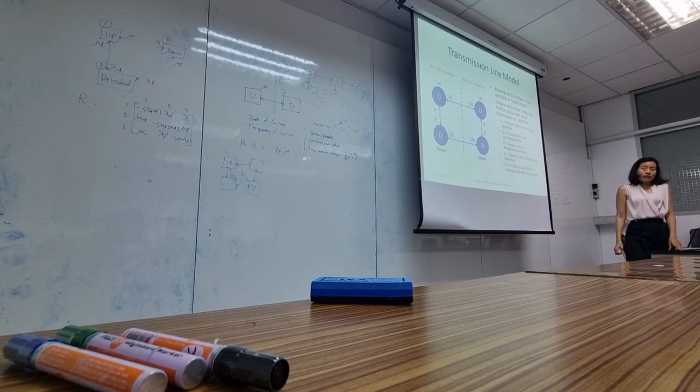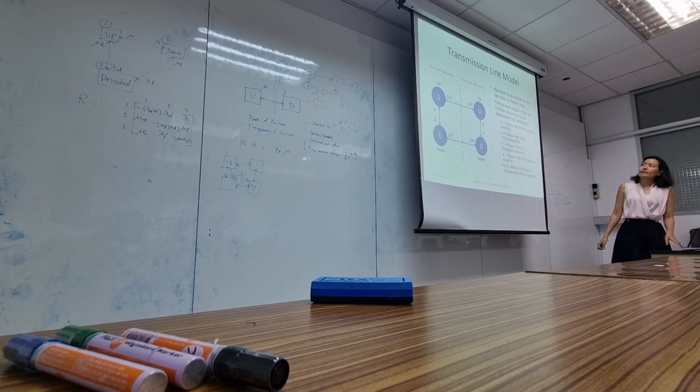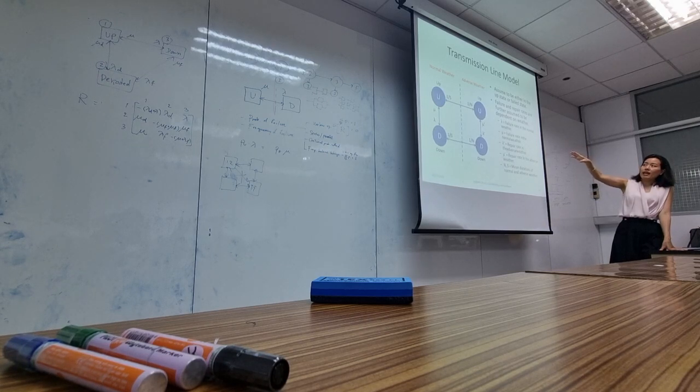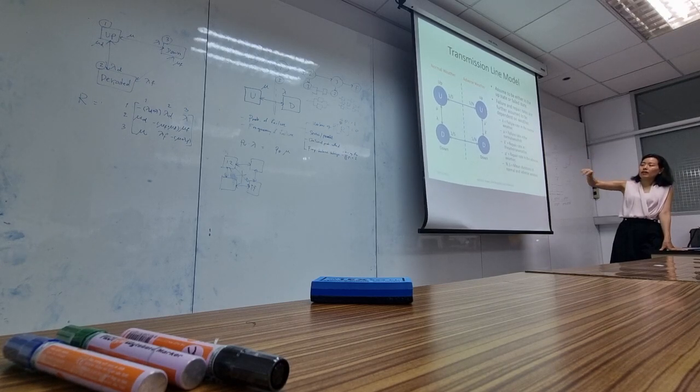Okay, forced outage rate. So we look at that example. For the transmission lines, they assume two states only. The up state and down state. Up state with full capacity and down state with zero capacity. But in most cases, the transmission line depends on the weather. The failure rates in normal weather are different from adverse weather. Okay, repair rate is also different.